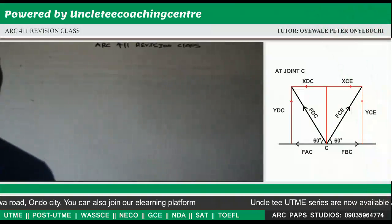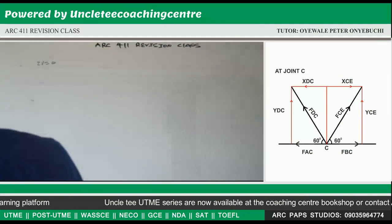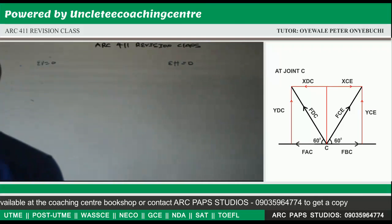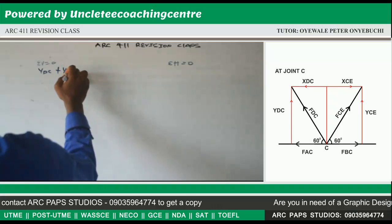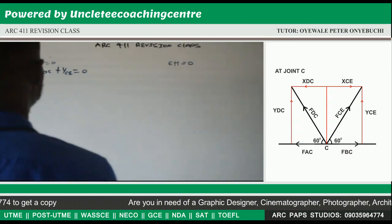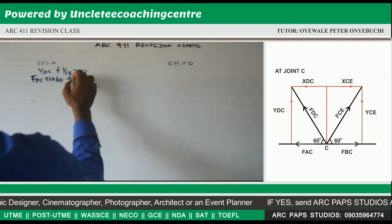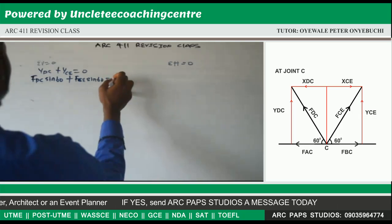Now let's go to joint C. Same approach, summation of vertical forces is equal to 0. Summation of horizontal forces is equal to 0. Now our vertical forces there, very easy. That is our YDC and our YCE. They are both positive values because they are facing the positive side. Now our YDC, FDC sine 60, our YCE, FCE sine 60 will give us 0.